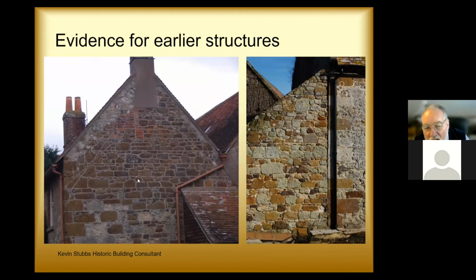And again, the wall can give you evidence of change. Here, 2 different techniques of construction with a butt joint in between, and you've got quoins here showing that in this original building, the corner was here with its quoins. This has been added to it, in a different hand, different period, different technique of stone walling. Here we've got evidence for change.